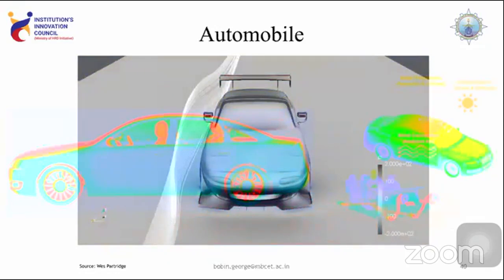Next comes the thermal management as well as the cabin comfort. Coming to the heat that is entering a system, here the energy equation comes into the picture in a large way. In the other two conditions, we will be concentrating only on the type of flow employed in the system, mainly for the aerodynamics aspect. And in the internal aspect also, energy was not considered because we were looking into what type of swirl was created inside. Coming to the thermal load management, as the energy equation comes into the picture, its effect can be modeled more realistically with the help of the K omega model rather than any other, along with the shear stress transport model.